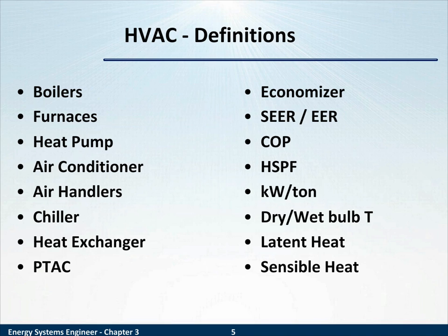A heat exchanger is a device used to transfer heat from one medium to another. Typically, in a heat exchanger, those mediums are separated maybe by a copper wall and a pipe. But not always. There are wheel heat exchangers where two gases, or air and another gas, exchange heat and mix, but typically they're separated.